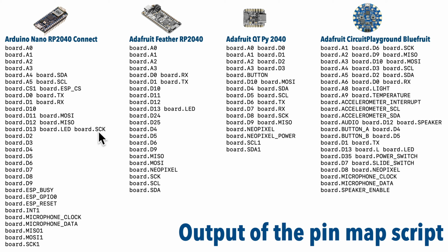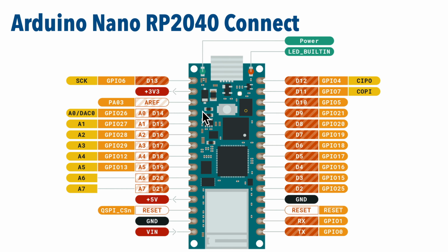We're not going to be working with that concept in the next few videos, so we'll table a discussion for now. But do be aware that if you use this board, if we look at the pin diagram, there is also a physical D13 pin. So if you plan to use the built-in LED light, you should avoid using pin D13 or vice versa.